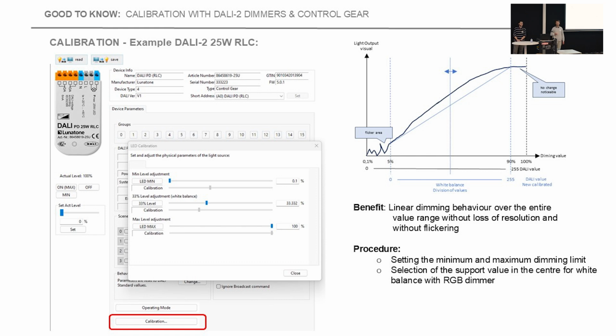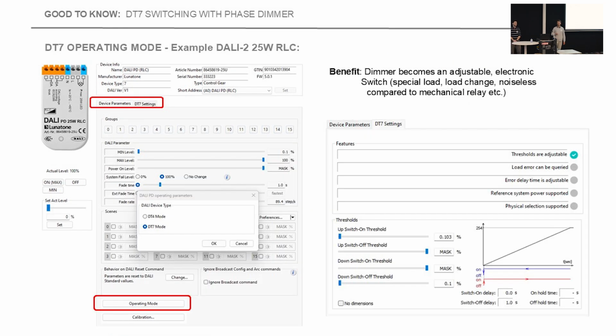Here you can see the cockpit setup, and then you can also use these dimmers, for example, in contrast to a relay module. As they don't make any sound, they can also be used to switch loads on or off, always up to their respective watts. So the PD300 can turn on or off up to 300 watt loads without making any noise.